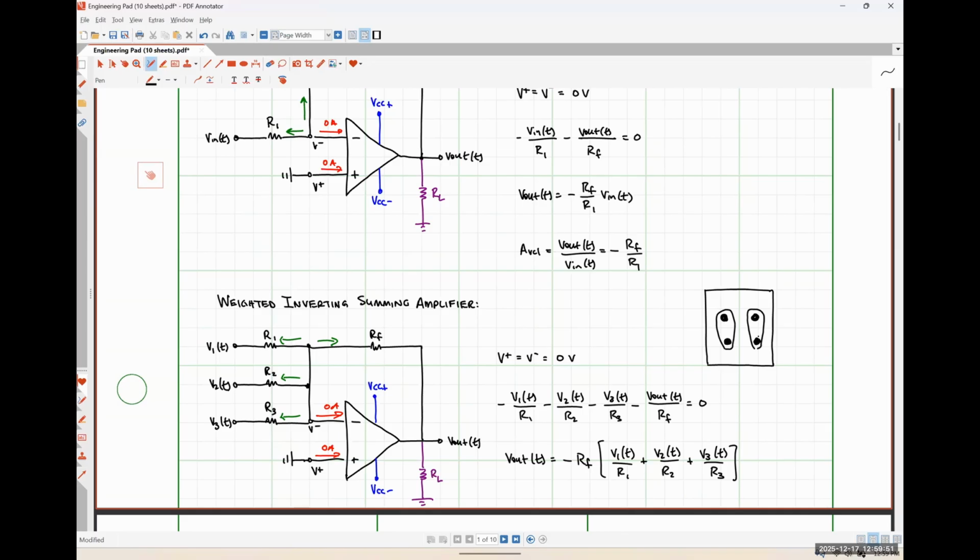All of those sensors connect to the input signals of a weighted inverting summer like this, and they're all scaled by the same amount so that when you add all of those signals together, it tells you your weight. For what it's worth, the weigh stations that you see leaving or entering a state by an interstate highway are based on effectively the exact same thing.